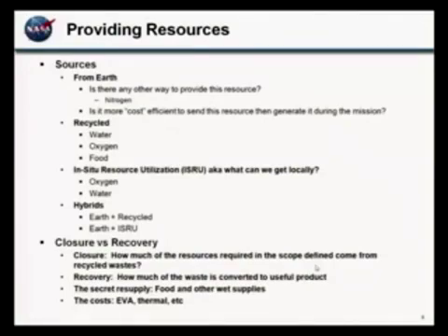If the outside environment is hotter than you want to be, you need to turn off your heat transfer. No amount of larger radiator is going to fix it. So they need to use water evaporation during those hot phases. Mars, conveniently, is somewhat more moderated than the moon. The hots aren't as hot and the colds aren't as cold. So you may not have that issue, but you may look into it for contingencies and things like that.